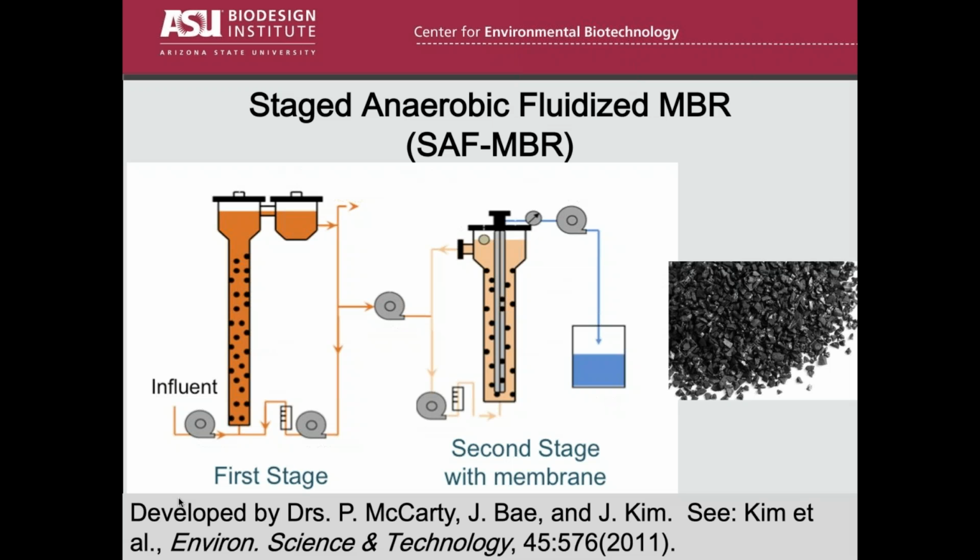And so what you have on the left side is an anaerobic fluidized bed where the fluidized medium is granular activated carbon. And granular activated carbon is lightweight, it has lots of macropores, great for harboring these slow-growing methanogens and other organisms. It's ideal. So you have on the left side a regular fluidized bed, and you get most of the BOD conversion to methane there.